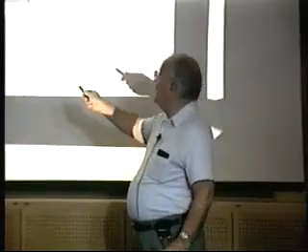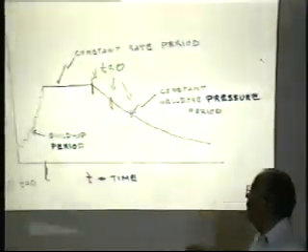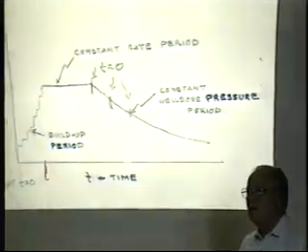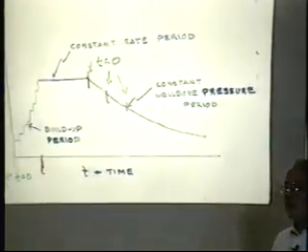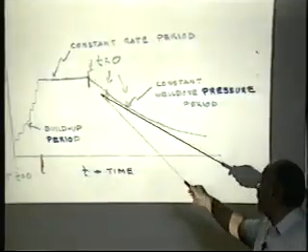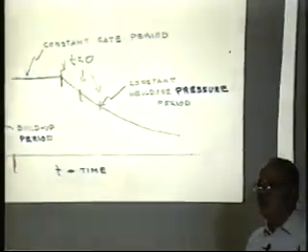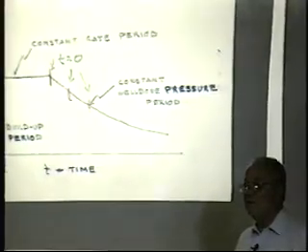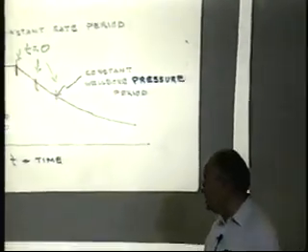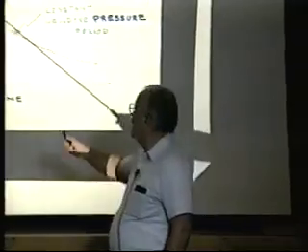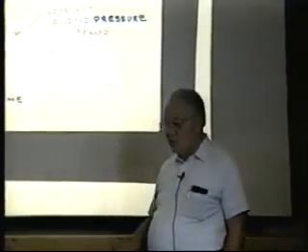So you need to start your t equals 0 for log rate time plotting at least when it's on decline, or actually any time afterwards is also okay, if you have enough data to uniquely define the value of b. That's the advantage of including as much time as possible, that you can get into the region on your log plot where it becomes unique.